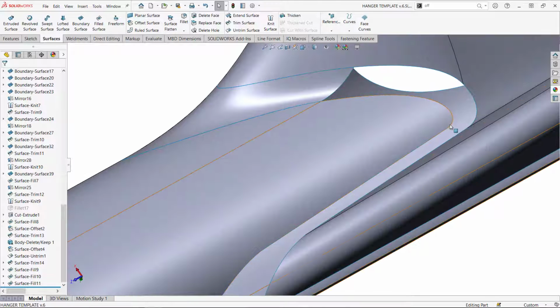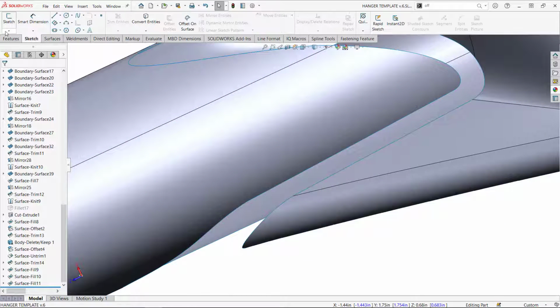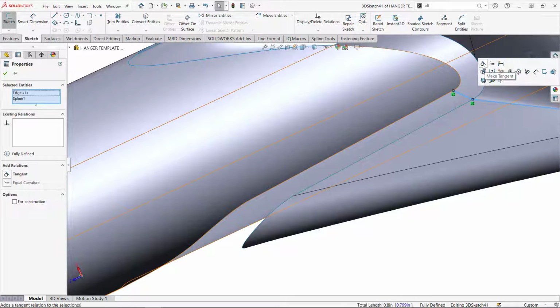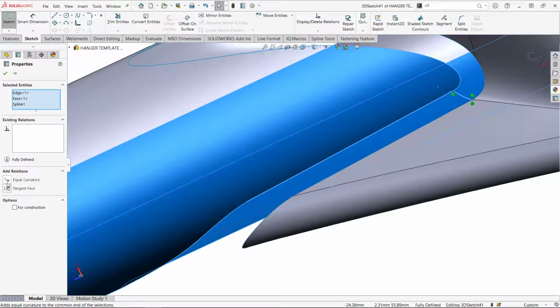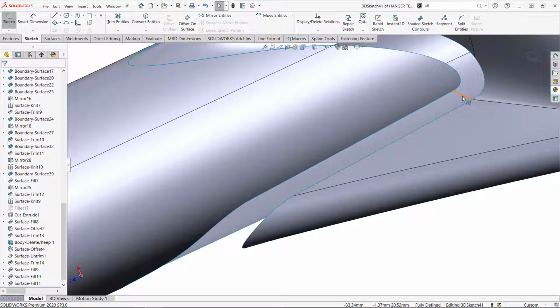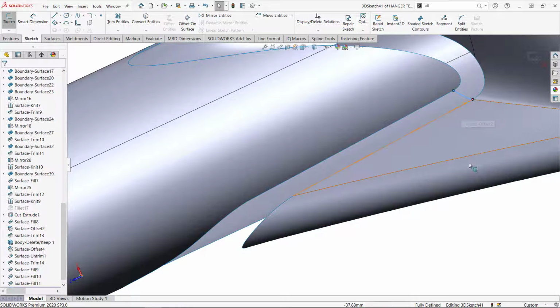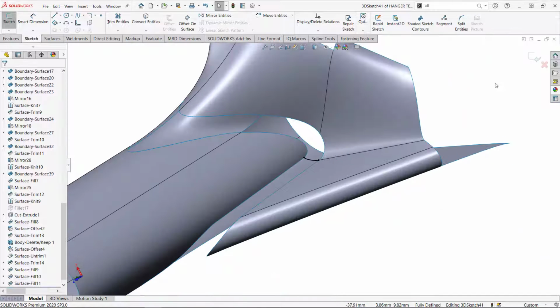Okay, let's take a look here. I see a point here that seems to correspond to this one. Okay, so another 3D sketch with a 2-point spline. Notice I'm trying to keep things simple. Tangency. And again, I'm going to go to the next edge for my tangency to face. I think this one has an inflection, but I don't think we can get around that. So, oh, no, it doesn't. It doesn't have an inflection point. Sorry, it was just the perspective.